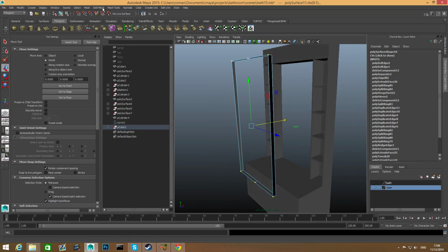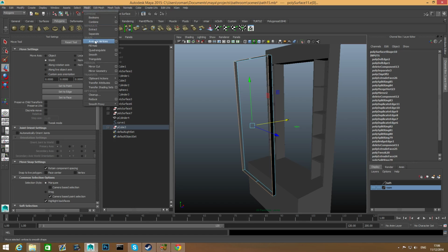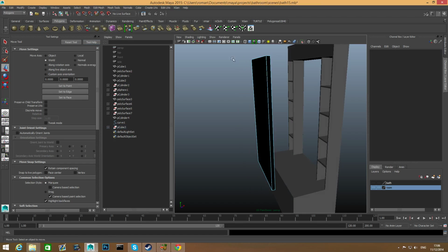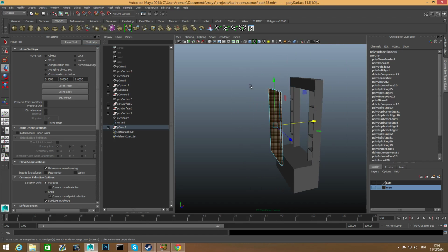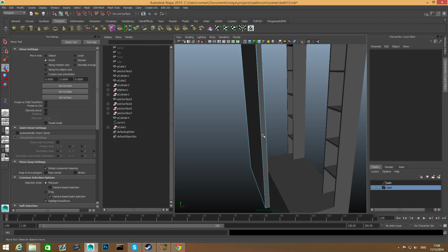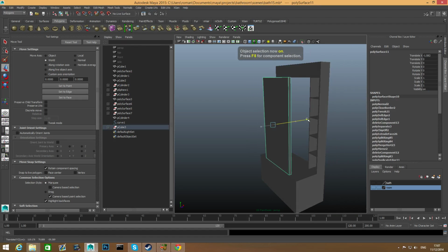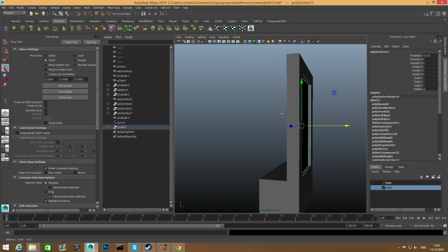I mean, why not? So let's just take this, right-click edge, double-click on this edge. Let's do mesh, fill hole. And here we go. We only need to grab all those faces. And let's grab all of them. Go over normals and reverse here because they turned black. So now I can press F8 and simply move this to the back here.